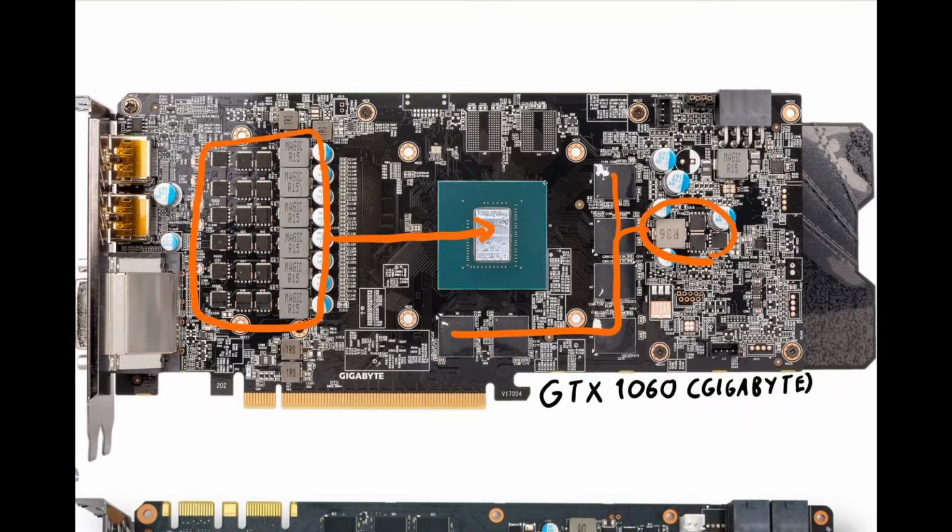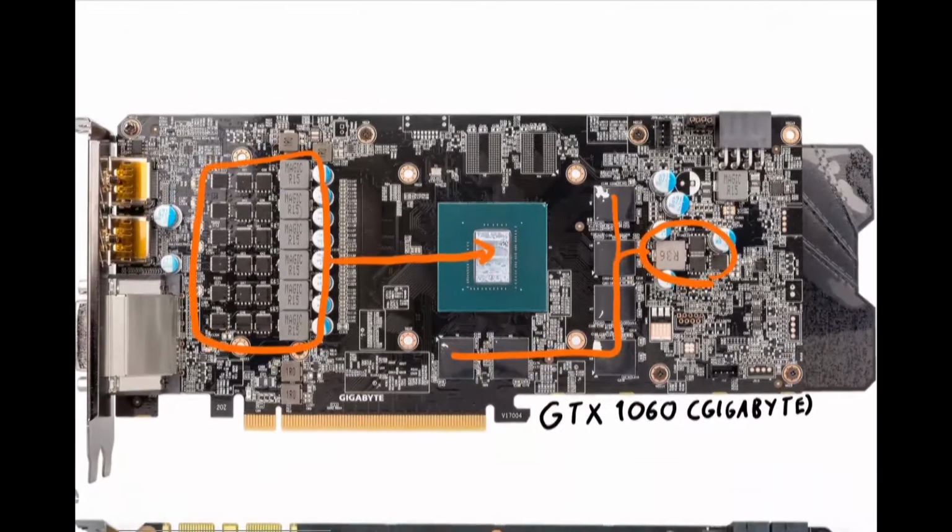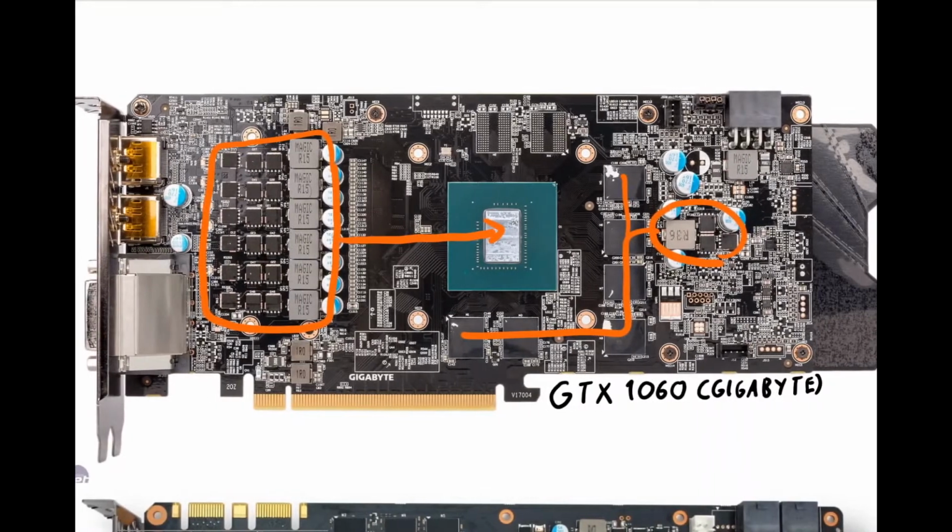This layout is actually pretty common for AMD's RX 400 and 500 series cards. If you have one of these cards, you will pretty much always have your vCore VRM on the left side, and then vMem and VDDCI on the right, like here. There are also certain NVIDIA cards like this GTX 1060, a lot of 1050s and 1050 Tis do this. The reference GTX 970 does this, if I remember correctly. There's nothing really bad with having the vCore VRM on the left side, it's just an uncommon thing.